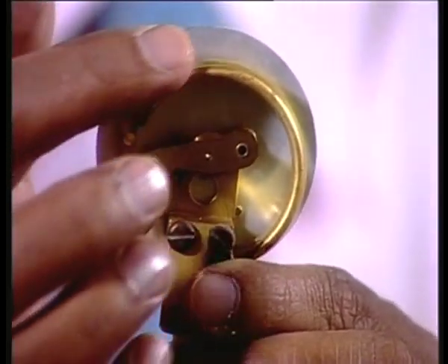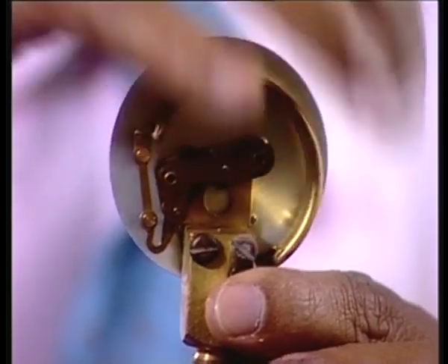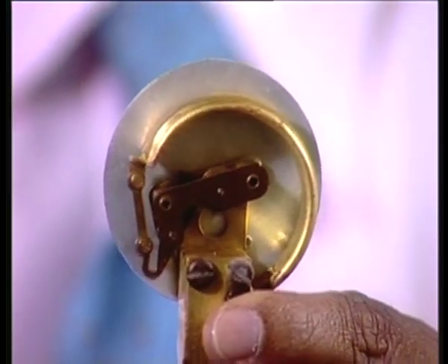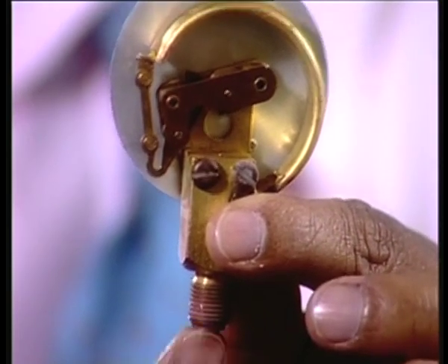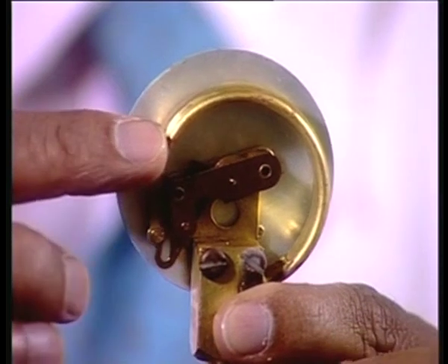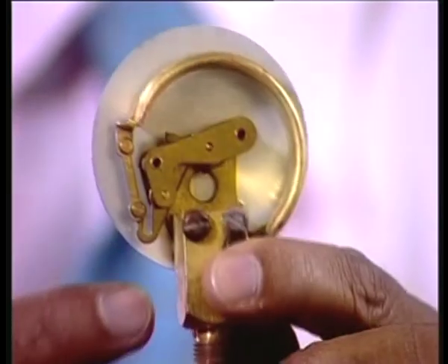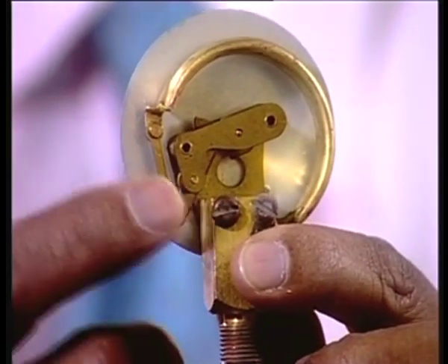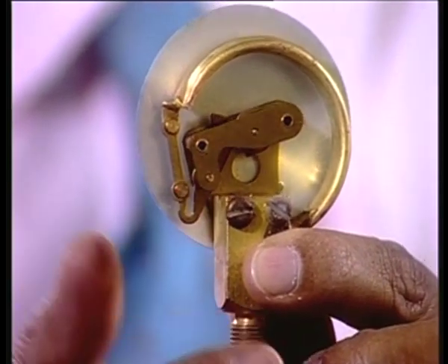This is a C-type Bourdon tube. You see this is a C-type Bourdon tube. The unknown pressure is coming through this region, and this side is closed. You see this side is closed, right? And with the linkage it is connected to a sector. The sector is here. Now what will happen?